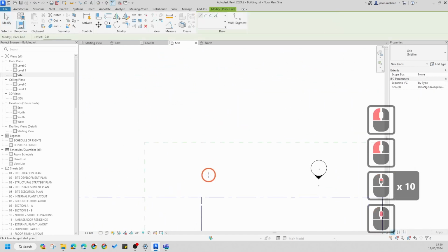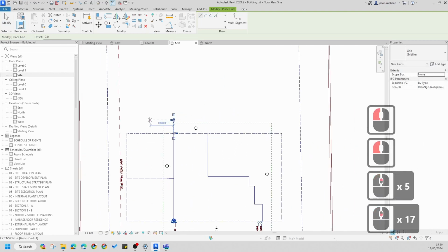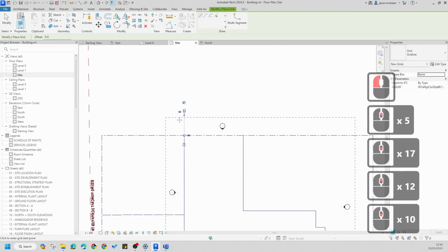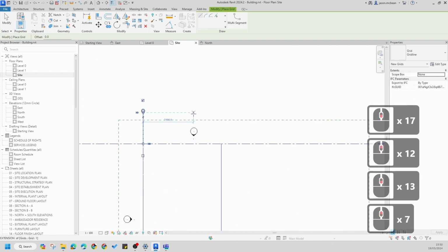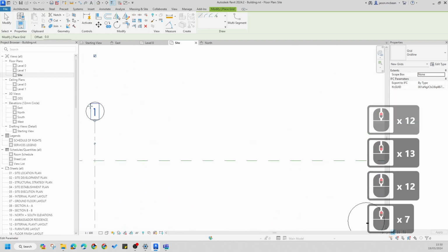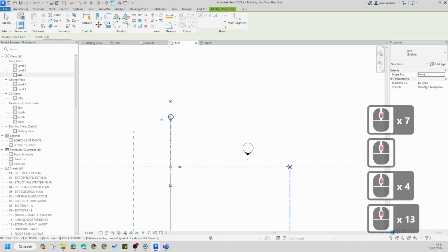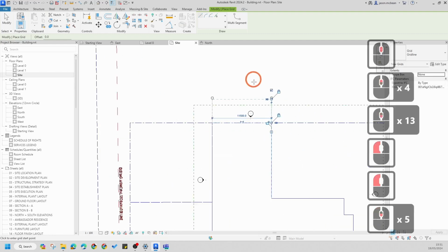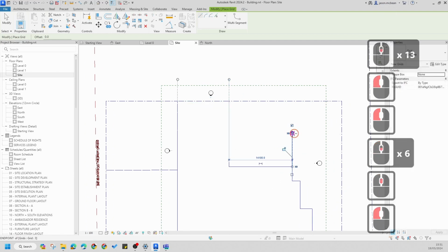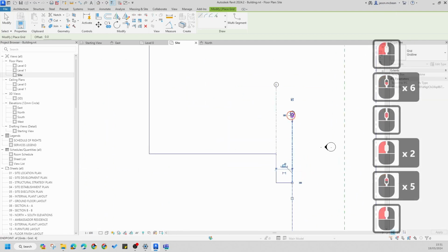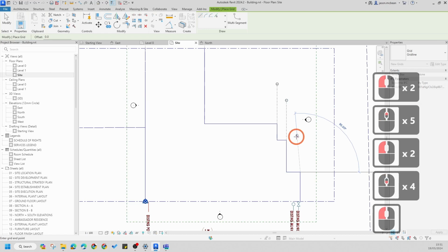Architecture, I'm going to go to grid. Now, when you first start drawing a grid, I'm going to select this point here and draw up, and you'll see it'll draw vertical. Now, horizontal, you might want to use numbers, and vertical letters. You need to pick the right method to do. So whatever method you started with, letters or numbers, you'll see it will continue using that method. So here I'm just clicking, dragging up, clicking, dragging up, and you see it's creating the levels as I want.